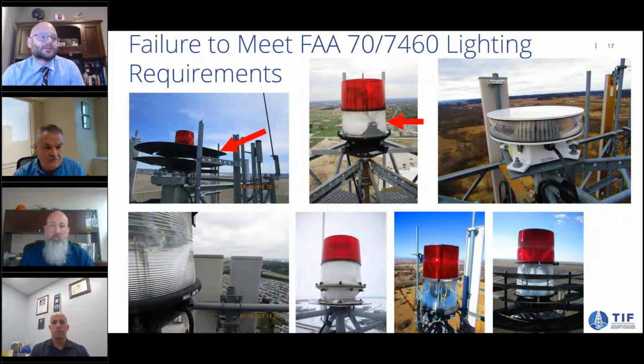Point you to that top left picture there. That's a light diffuser or a light shield, whatever you want to call it. It came from good intentions, trying to help farmers maybe not have to see the light all the time. The problem is it does put this particular structure owner into regulatory noncompliance. There's substantial fines that go with that, and there is a safety aspect for the men and women that fly. This lighting is to help prevent collisions and those sort of issues.